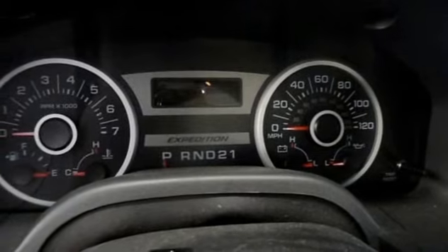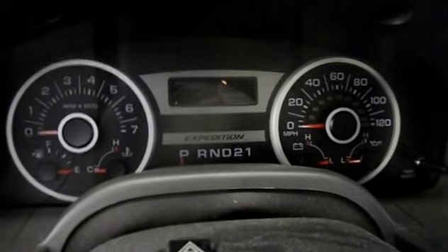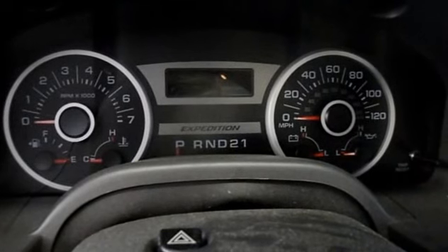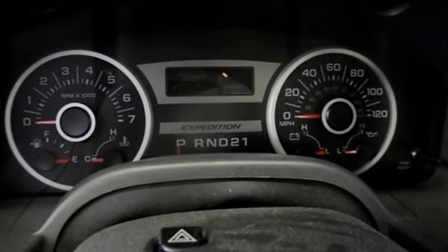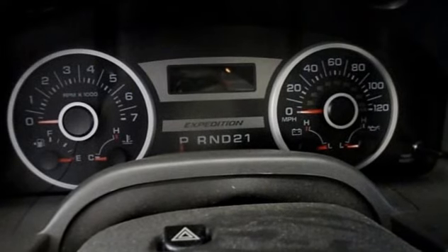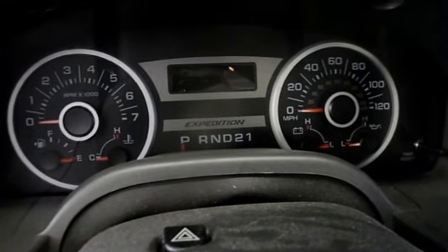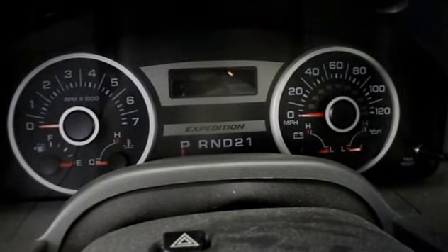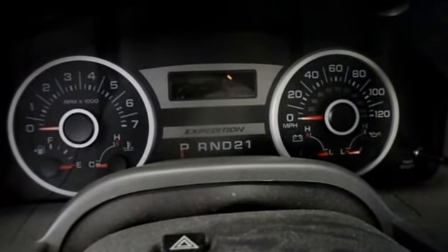Okay, one thing I might add too is that once that check engine light comes on and you notice that your transmission is not shifting properly, don't drive it. The more you drive it, the more damage you're going to do to the trans. So ideally, if it starts to slip and you feel something not quite right, get it in, get it checked on a computer, and take care of it in the early stages. It'll avoid putting a very expensive transmission into it.